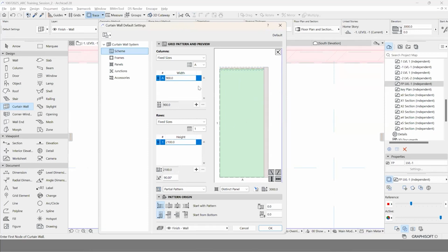But before that, one last element to cover here, that is the sizes. So there are 3 options when it comes to the dimensions that we see. One is fixed sizes. So let's consider you are doing facade paneling and you may have fixed sizes of panels that you need to place. At that time, we go for fixed sizes and put the dimension, so that if anything is smaller, it will be a cut piece. Anything bigger, it will try to put that particular pattern in that, and whatever is extra will be used as a cut element.